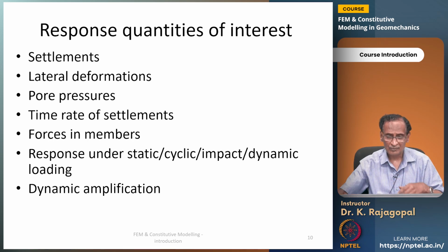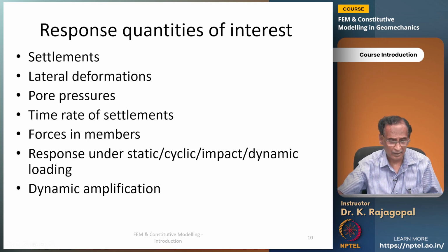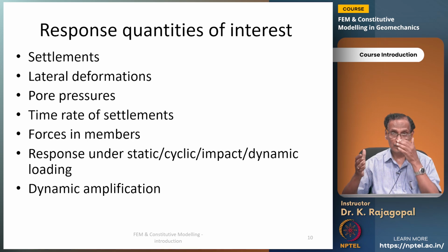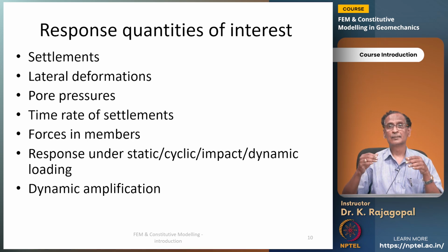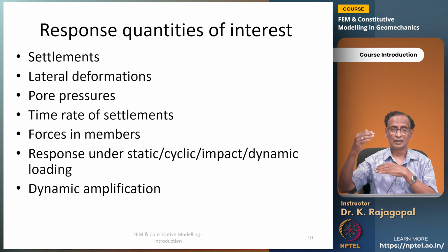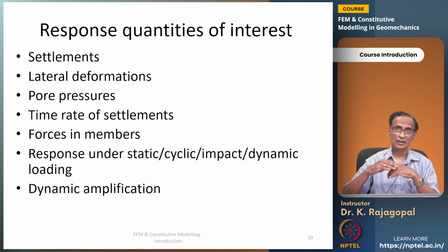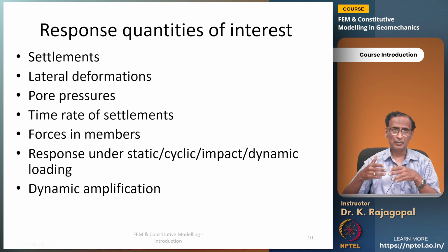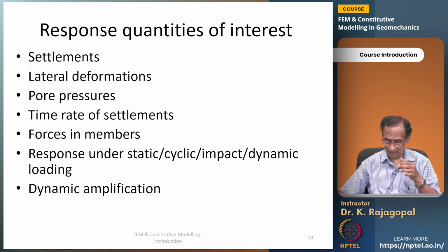And when we have impact and dynamic loading, we should be concerned about dynamic amplification. If there is any resonance, a frequency match between the structure and the loading, your response might be amplified, so your forces may be higher and your displacements may be higher. All these things we should be able to predict through our numerical modeling or finite element analysis.